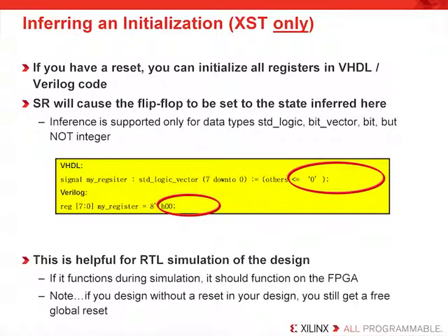Initialization of flip-flops in an FPGA is important for behavioral simulation. In this example, we have behaviorally coded a reset in our HDL. This will allow the simulation to show clearly what condition each flip-flop is in after power-up. Now, synthesis tools will react to this code. Most people assume that this is unsynthesizable code, but it will affect the INIT value of the registers because that is tied to the register's primitive.